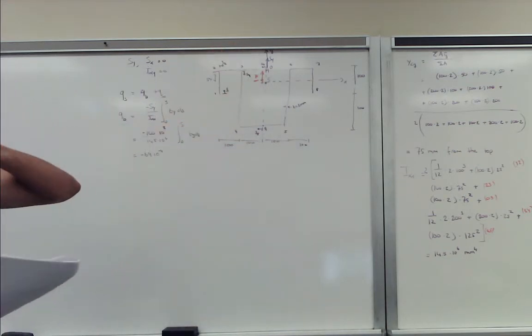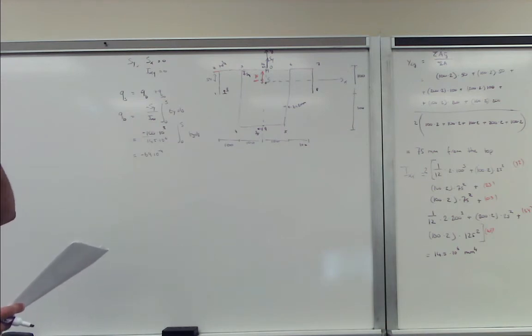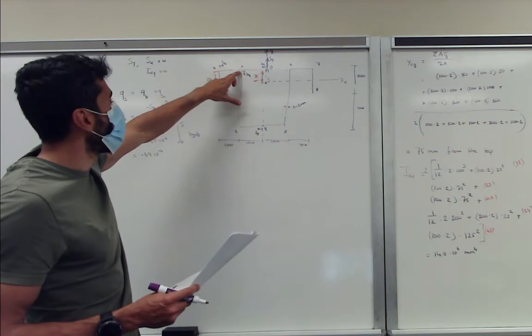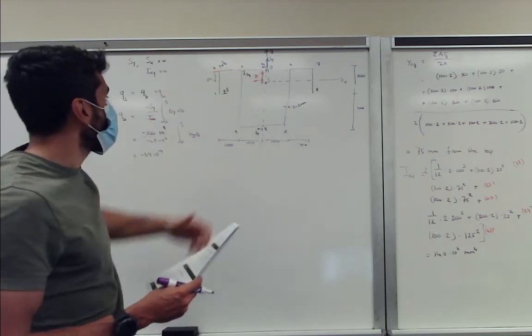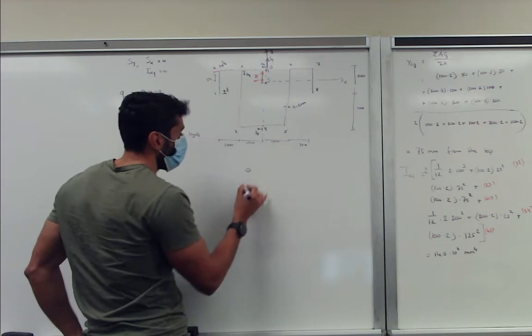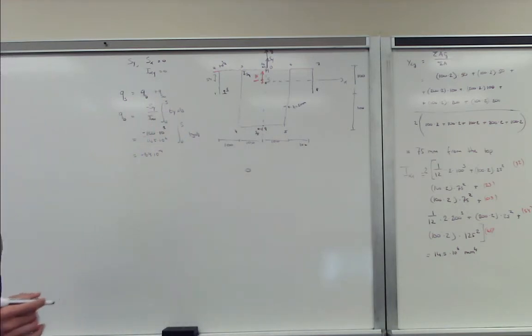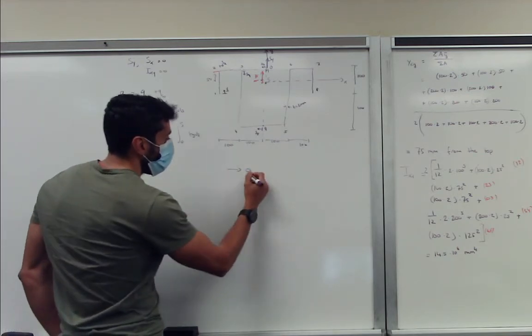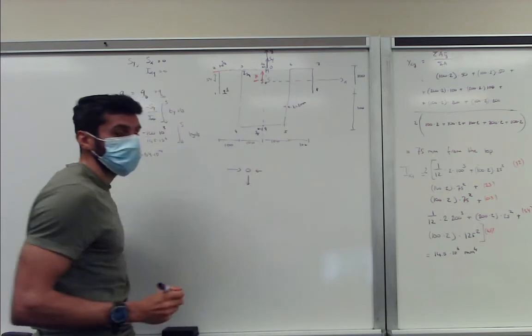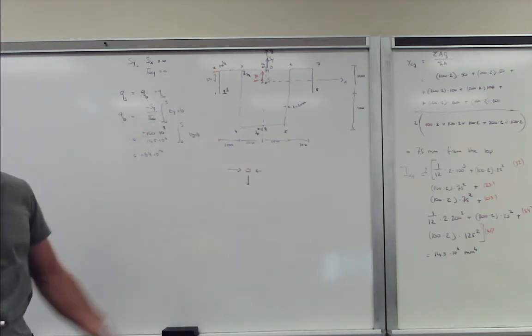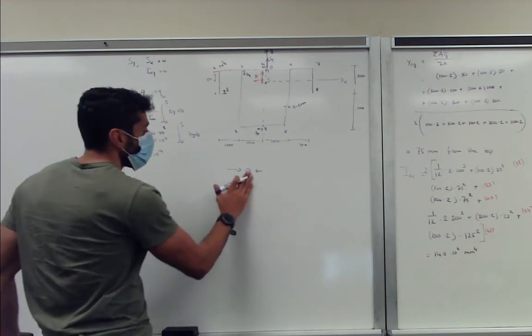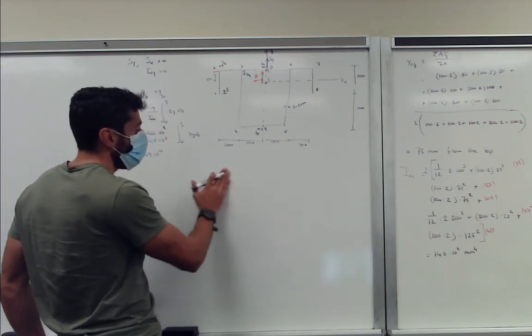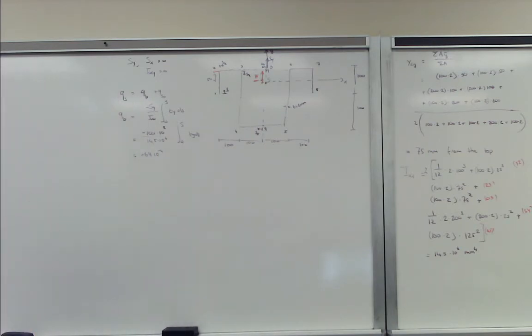So no, because you don't know what the total contribution at point 3 is yet. You have to see every intersection as an inflow. If you have a T section, there's a shear flow coming in from this side, and if you go downwards, you also have a shear flow coming in from that side. So you have two unknowns in that case. You need to know the total shear flows coming from a 0 point, a starting point, before you can continue. So the idea is to cut the section somewhere where there are intersections.